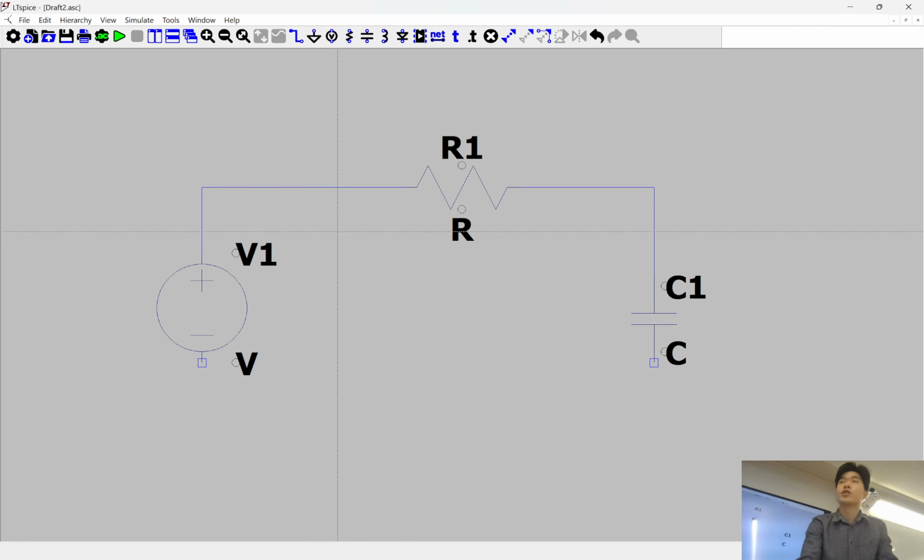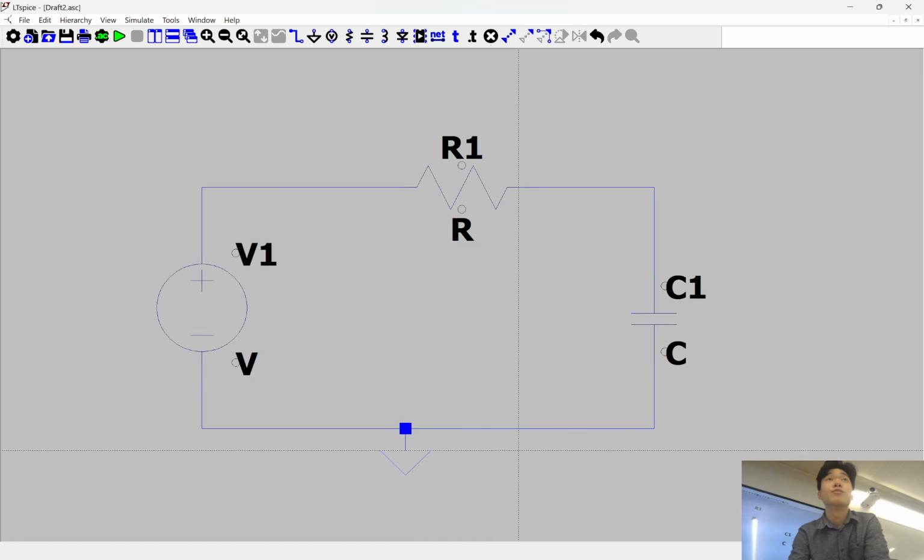This particular version, which I think they're updating most systems to, now uses W. And that's just my circuit. Something to remember as well is to connect to ground, otherwise you'll get an error. You can do that with the hotkey G. And that's our circuit.